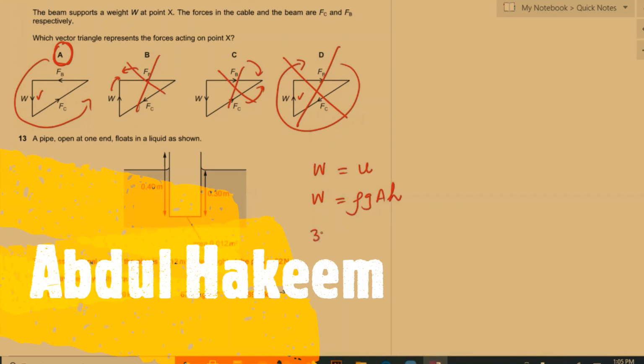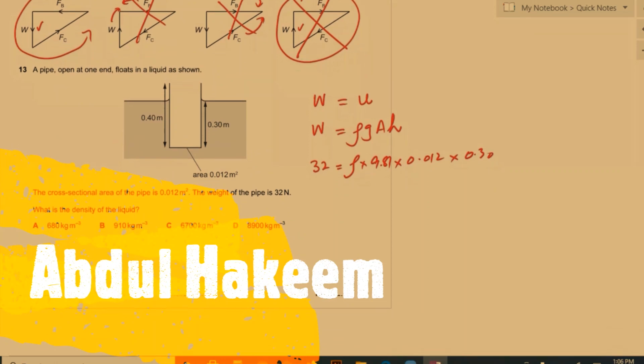So the weight is given, which is 32, rho g value 9.81, area is given, which is 0.012, and the depth of the liquid, not the depth of the tube, because the upthrust is exerted by the displaced water. So it is 0.30. By calculating this, 32 divided by 9.81, 0.012, 0.30. This is the density, and the answer will be approximately 910.